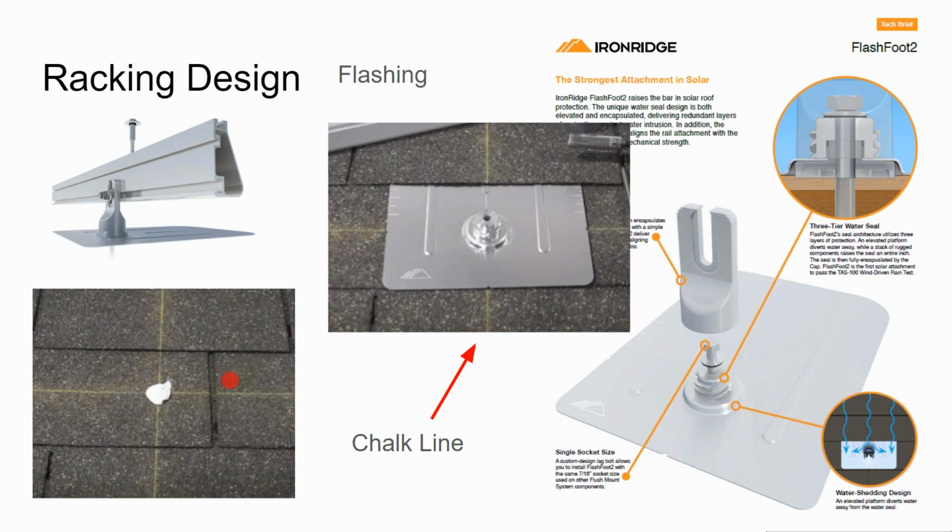And that takes practice, to be able to identify rafters with a hammer. Then you get a pretty good guess of where that rafter is, and you drill a hole. Hopefully you hit the rafter. If you don't hit the rafter, you stick a wire down the hole and give it a twist and see how far away you missed it from. And then you take caulk and goop up that hole, and then it gets covered up with your flashing. So most installers are going to be poking a couple of holes in your roof that won't get lag bolts screwed into them.